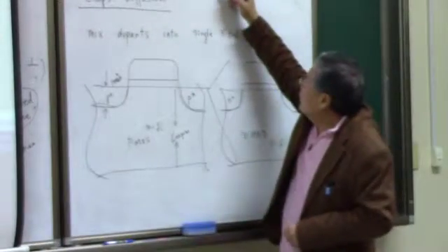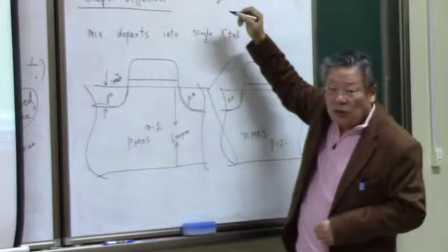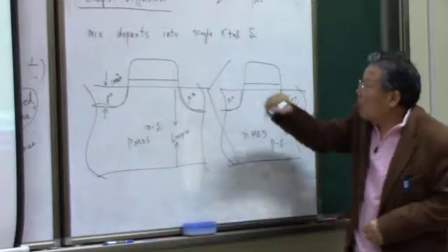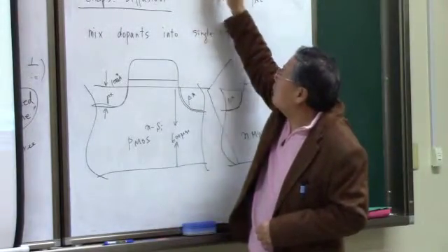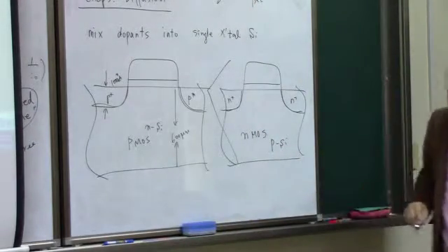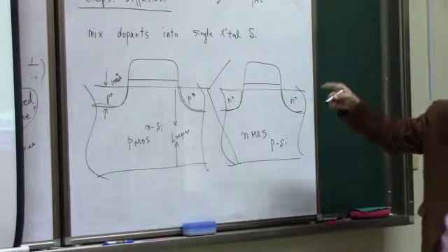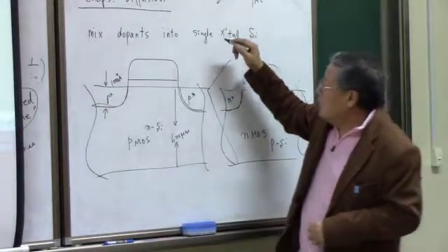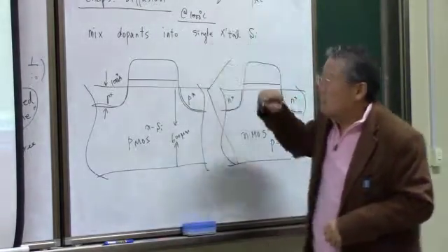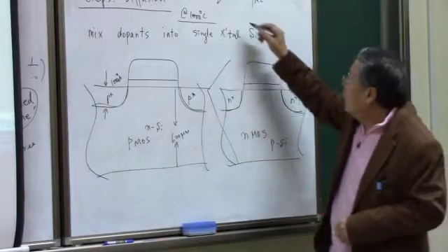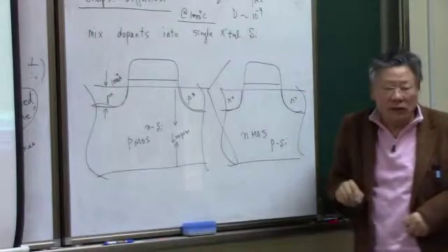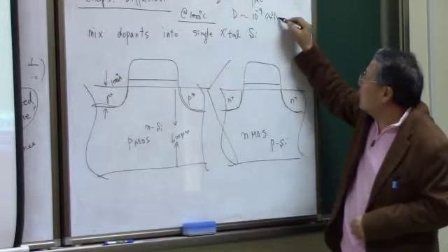As you see, the diffusion coefficient has a unit of centimeter square per sec. Okay, so the diffusion length, as a rule of thumb, you have to multiply the time and the diffusion coefficient, and the square root of that is the length. So let's see, at 1,000 degrees centigrade, this is a pretty high temperature, and the diffusion coefficient is typically 10 to the minus 9 or something in a solid state, centimeter square per sec, okay?